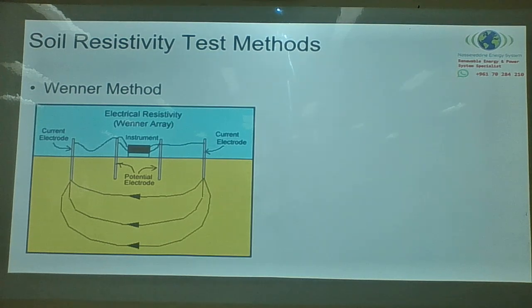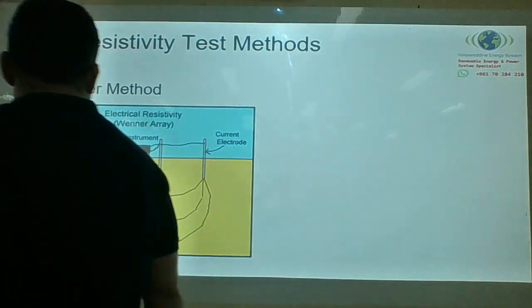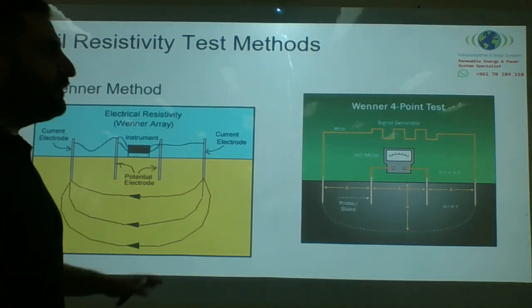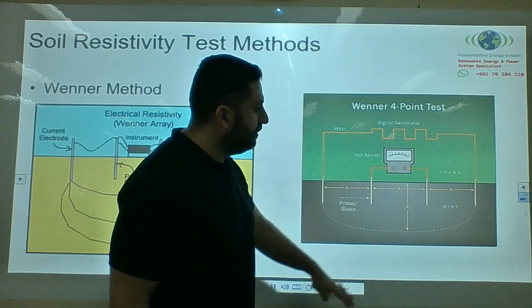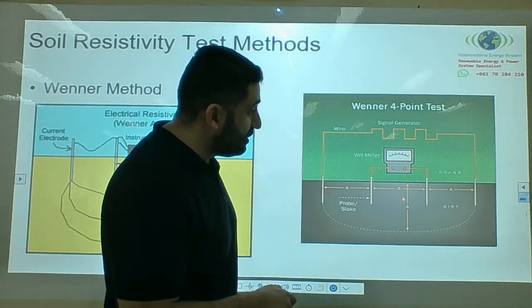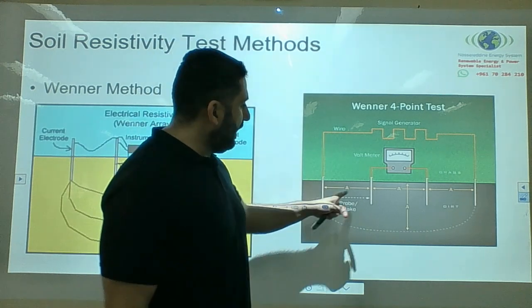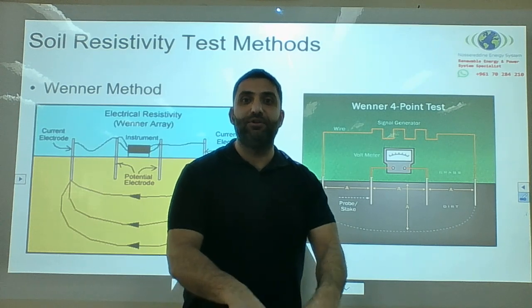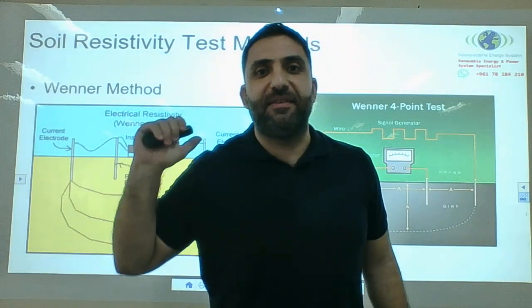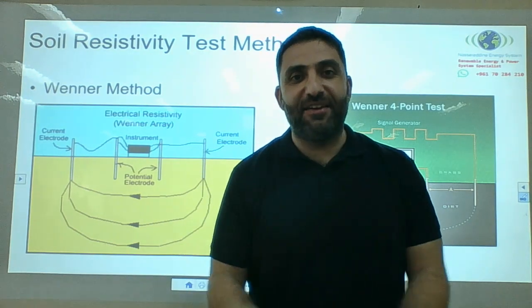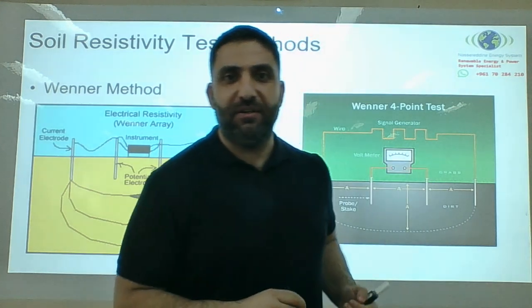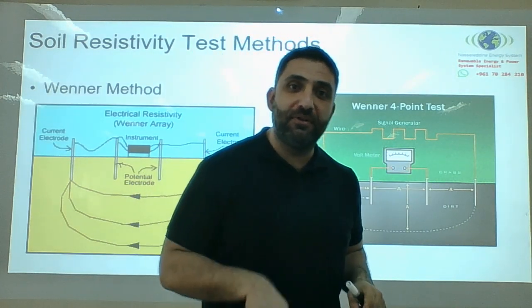This is the Wenner method: voltage and current probes, measuring the current and measuring the voltages. In theory, if you have one layer of soil, you are measuring a distance down. That's why, by making A larger, in reality I'm going deeper into the ground. You can use this method to determine the type of layers underground. And if you have a very sophisticated machine, it will give you very good, accurate results for the bottom area.